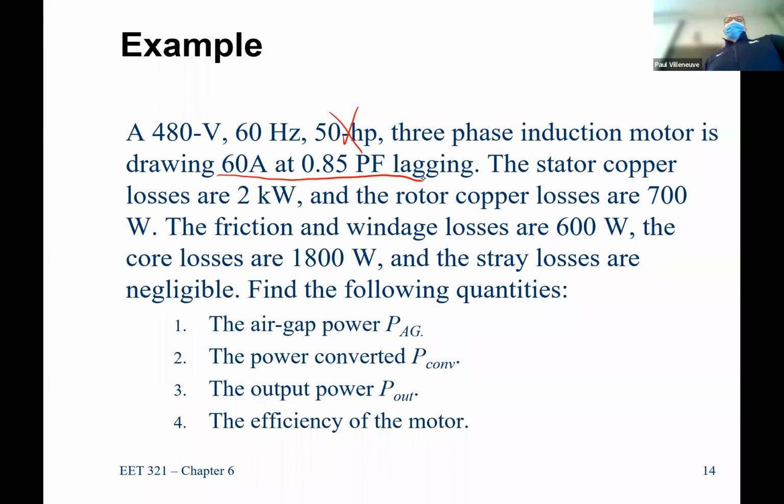That's a great question. The question is whether that 0.85 power factor depends on the nameplate of the motor, and the answer is yes. The reason is the load is purely real power, right? The load doesn't consume VARs because that's power that has to go back to the grid. So the load is literally just real power. That power factor is determined by the construction of the machine.